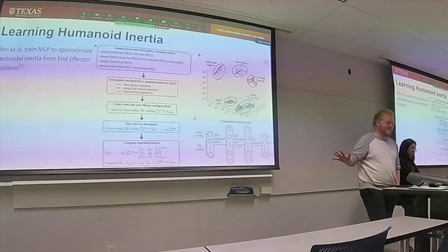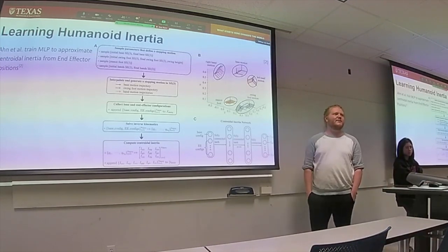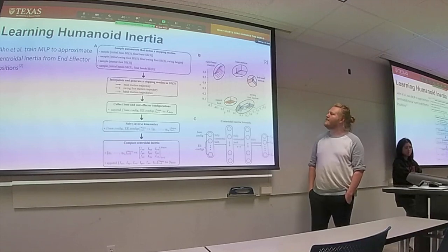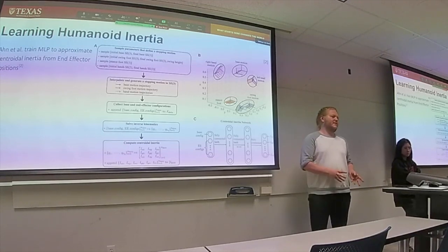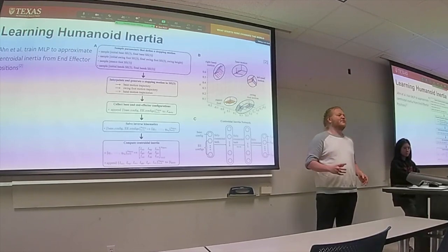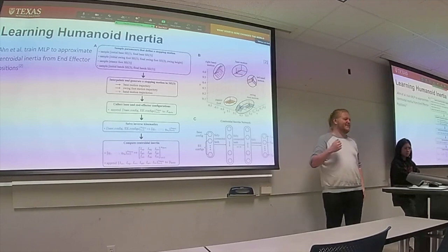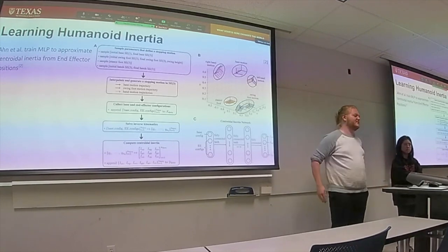All right, so on the other side, I'm involved with the Human Centered Robotics Lab, and something we've worked on in the past is, there's a lot of research groups with quadrupeds, there's not that many with bipeds. For quadrupeds, it's a pretty valid assumption to just have a constant inertia. We call it the potato model actually. When the robot's doing MPC online, it just has one inertia, it doesn't worry about the position of its legs, it simplifies things a lot.